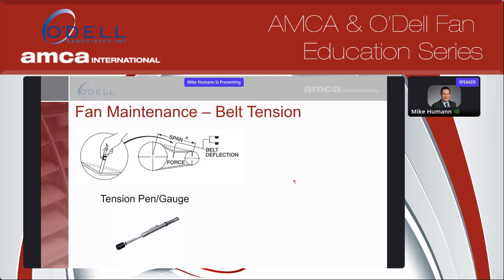One way to measure that is a tension pen or gauge. That's a nice tool to be able to measure belt tension and make sure you're in the right range. You see a lot of people will use their fingers as a tension gauge, and that's really not the best approach because your finger's not calibrated. The tension pen or gauge is relatively inexpensive and an easy tool to carry.